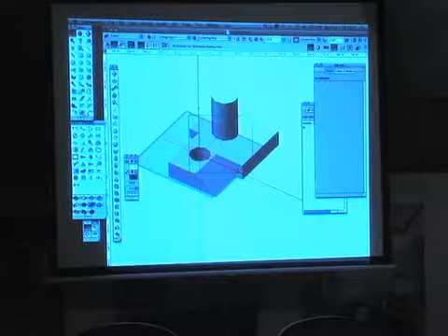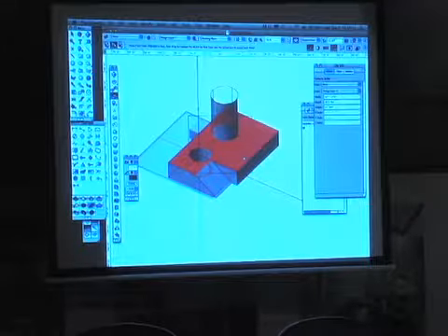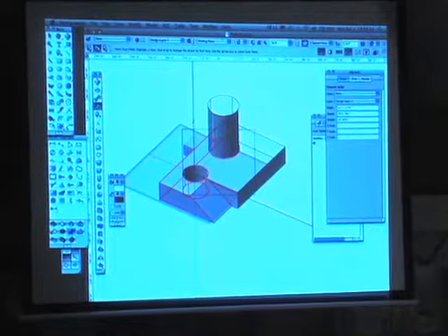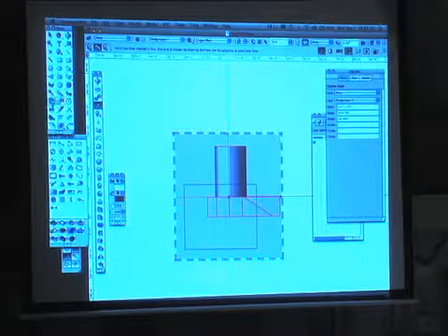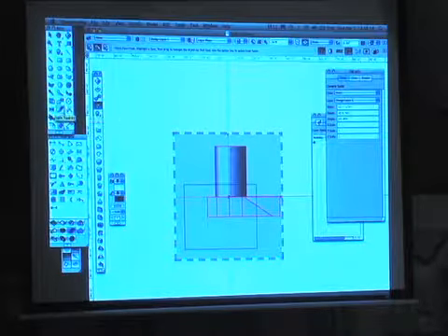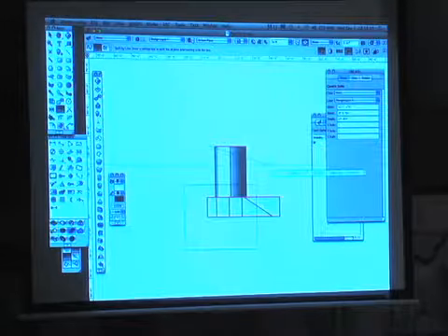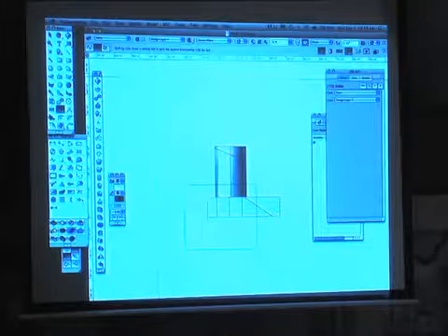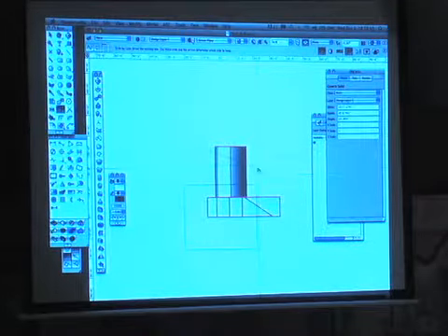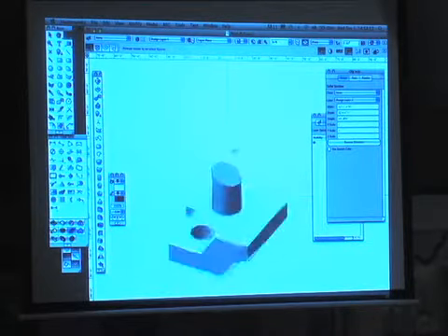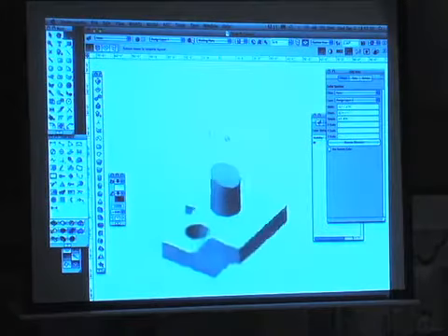You can begin to. Does split line or split still work with this? I actually think so. If I go to a front view, yeah, that still does work. So if we use the split line across this, let me undo that. I want to pick the third mode here where I can just draw a line across here and subtract that away, and begin to chop things off with the split line tool.